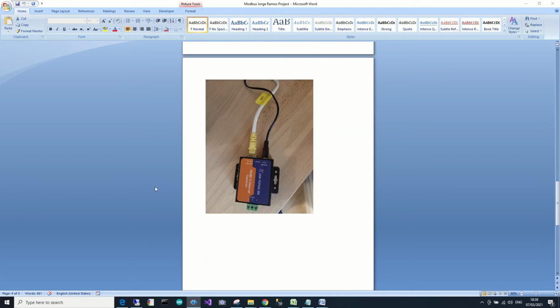And it's very much the same when you use, say, an Ethernet to RS485 converter. You basically have these 3 pins here, and they go out into the device, and then you have a device which is accessible over the network. You can use a standard Modbus TCP server, but you can also use something called a virtual COM port as well.